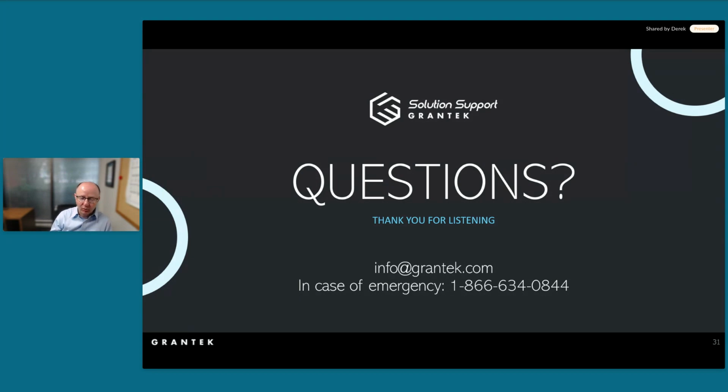But the number one tool I recommend is if your maintenance teams are able to be in front of the panel or in front of where the equipment and the electronics are, but also have access to the HMI. It gives them visibility to see the alarms, see what's going on, have an overview of that system, and as they're troubleshooting, see in real time how it's affecting everything, knowing if it's safe to do so. I find that's a lot better than just them having their laptop and their tool.